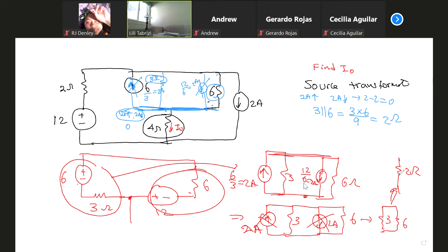I do advise that you keep it in mind, and in future, if you need any circuit, always check to see if you can apply source transformation, because you don't even write any equation. I'll show you here. You can compare it, because I'm going to apply nodal and mesh later. I'm not writing any equation here. I'm just making a transformation, simplifying to 2 ohm.